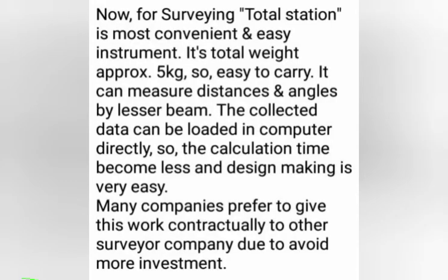There are four types of total station. They are scanning, robotic, autolock, and total mechanical. It is a combination of an electronic theodolite and an electronic distance meter, EDM. It measures in two ways, using the traditional and still more common prism or through reflectorless technology.